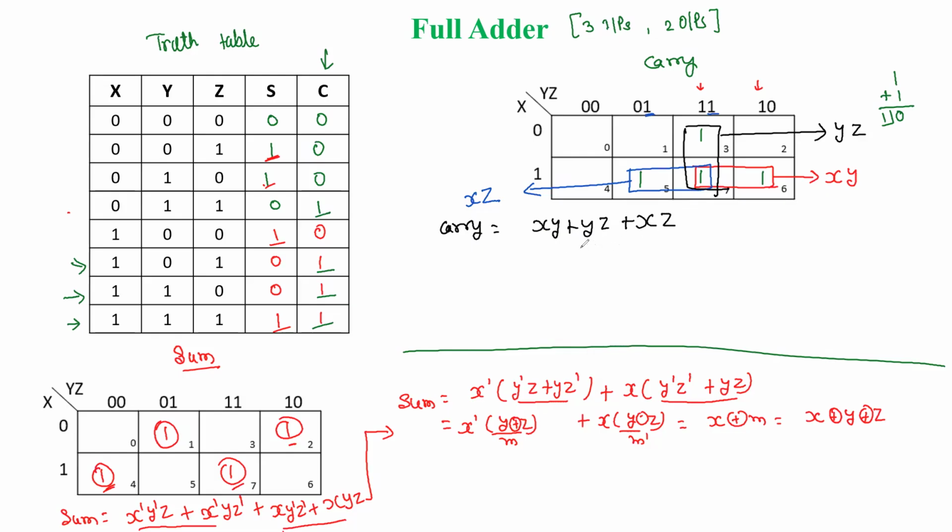Now this also we can simplify further so that it will look in the simplest way, so that it will be easy for us to implement. We can minimize the number of AND gates here. If you see, in this case this xy is the same as what we have in the case of the half adder. So this full adder we can see as the combination of two half adders. On that line we are trying to arrange these terms here.